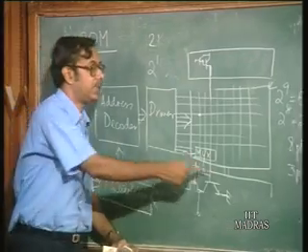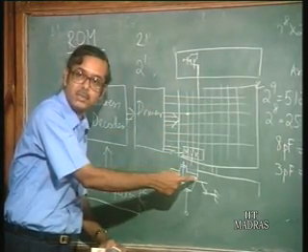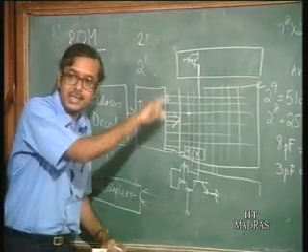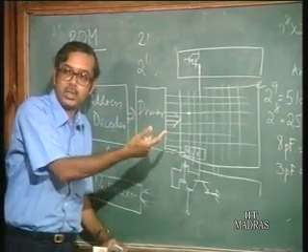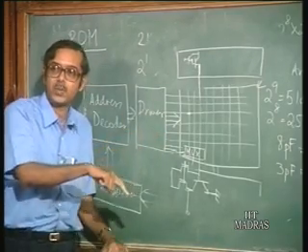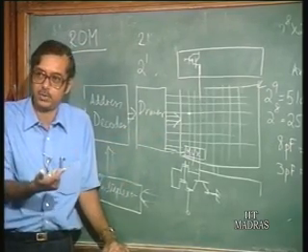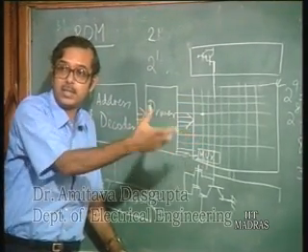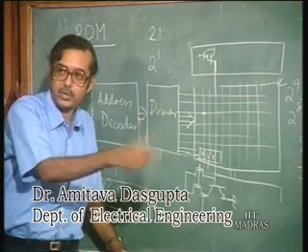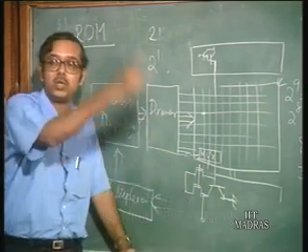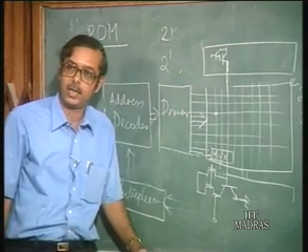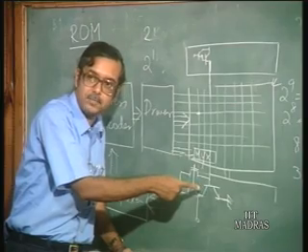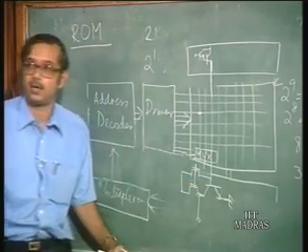Again, the maximum voltage this bit line can have is around 0.8 volts. So, when you are pre-charging or discharging the bit line, the voltage swing on that line is limited to 0 to 0.8 volts. So, you do not have to charge or discharge this very large capacitance through a high voltage, whereas if this was a CMOS inverter, it had to go all the way from 0 to 5 volts. So, that is the advantage: the voltage swing on this line is less, so you can have faster operation.